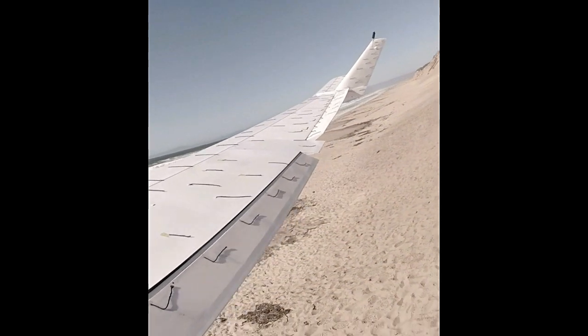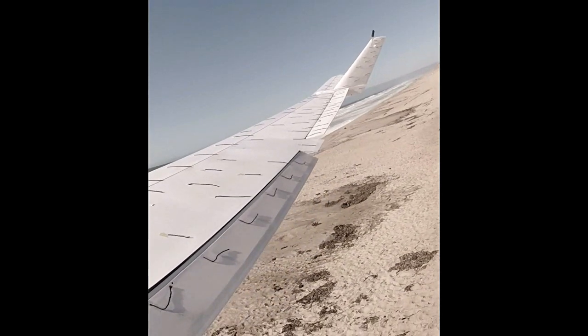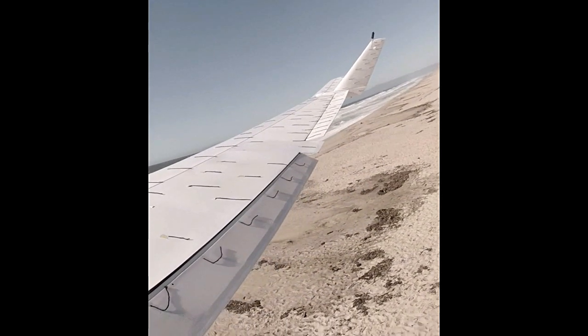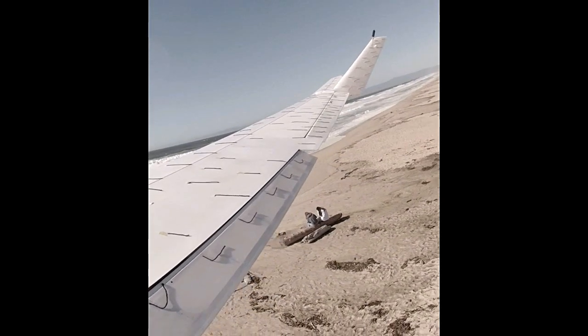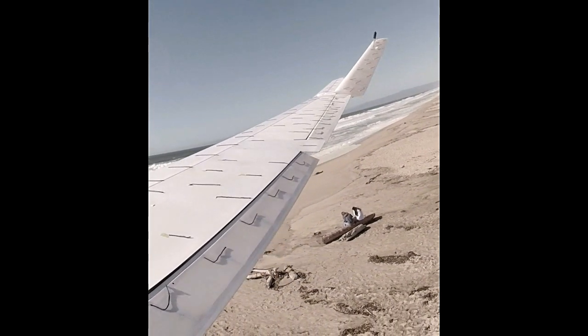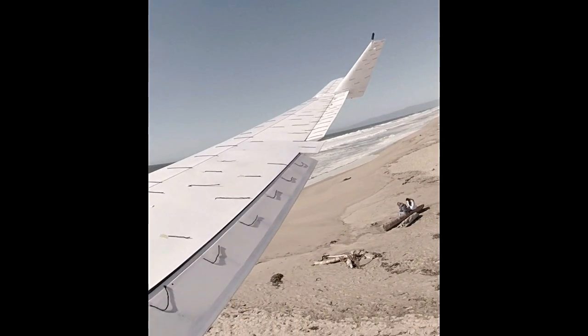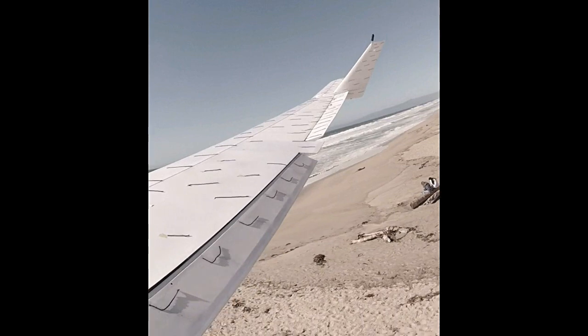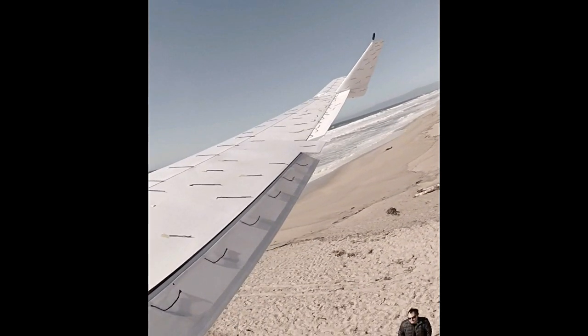That causes problems. Here I'm topsiding the stick to prevent overbanking. The same flight, so this is where the other wingtip's very close to the sand. There we get neutralized out. And a little bit of down elevon there to keep me in the turn. Don't want to go in the water. And there's the start of another stall with the elevon up.